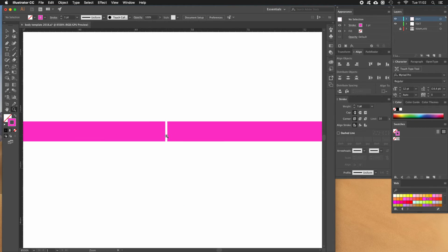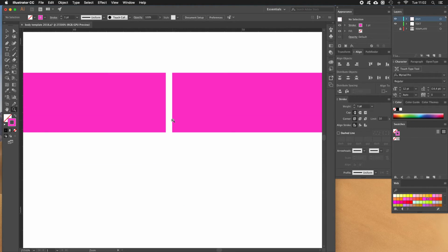All I do is, I select my direct selection tool, which is this one, the shortcut for that would be A. I select my first line, and you'll see my anchor point is over there, and I hover over my second line, my second anchor point would be over there. So all I have to do is hold Shift and left click again so that both objects are selected.